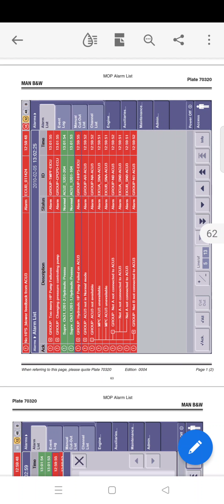Alarms presented in the alarm list can be found in 3 states: alarm non-acknowledged, alarm acknowledged, and normal non-acknowledged. So three types of alarms are there: alarms which are not acknowledged, alarms which are acknowledged, and normal condition, the alarms which have become normal and are still not acknowledged.